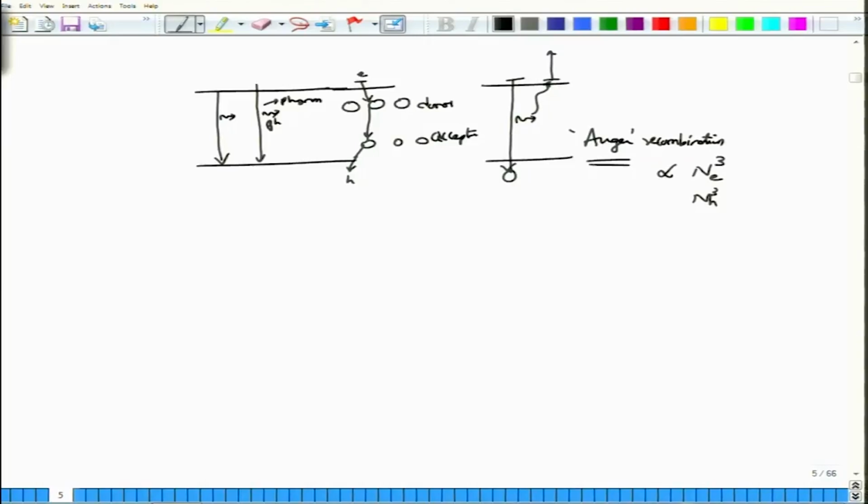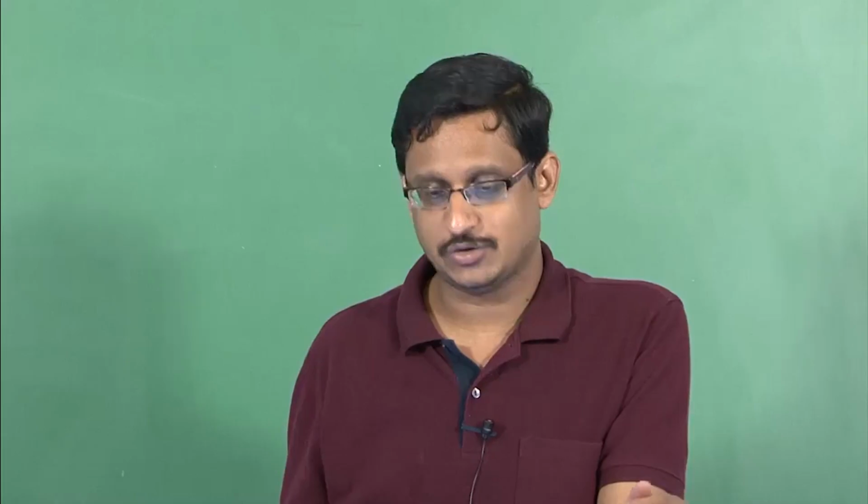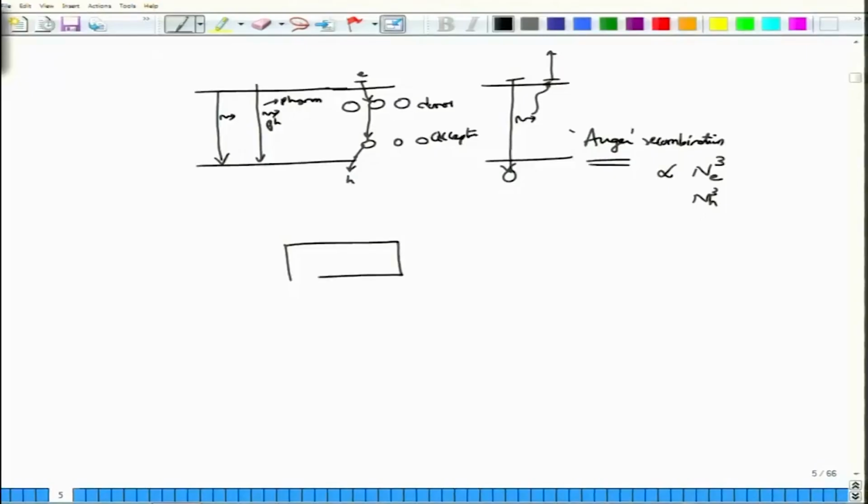So, these are all the different types of recombinations that may happen, but in reality we will not really be studying these recombinations in such detail. To study this would be a subject of its own, and quite a difficult one. Therefore, we will not go into those details in this course, but what we want to understand is how to relate absorption and gain of a semiconductor material, and to do so, let us assume that we are working with an intrinsic semiconductor. Here is my shorthand notation for a semiconductor. Sigma denotes conductivity or conductor. This is not a standard notation; I am just using it to avoid writing conductor everywhere.